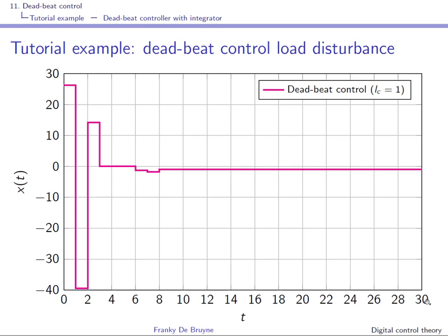This is again the control energy coming from a Matlab simulation, as you see it only at the sampling instance. Here you can see that the output of the controller settles to -1 to compensate for the load disturbance. As we have one integrator in the system, the output settles to a constant signal.